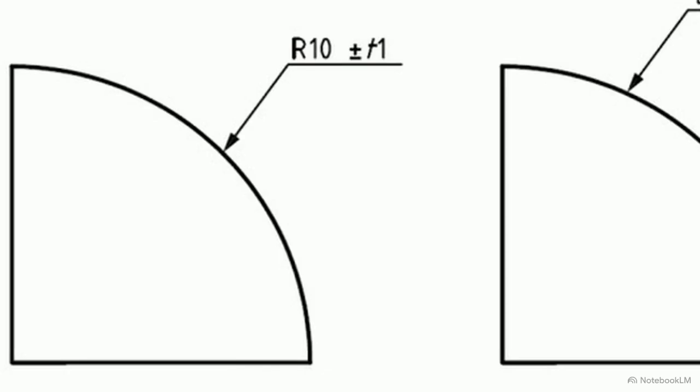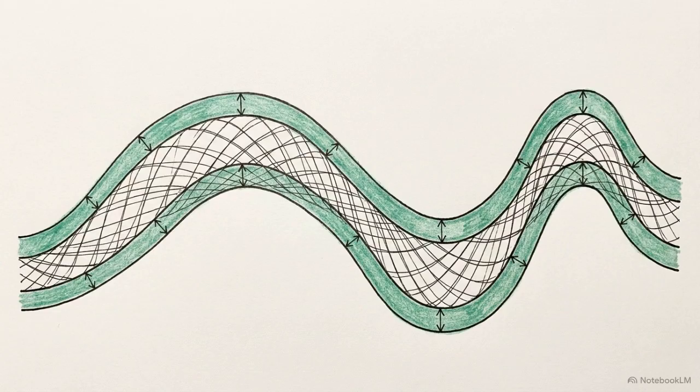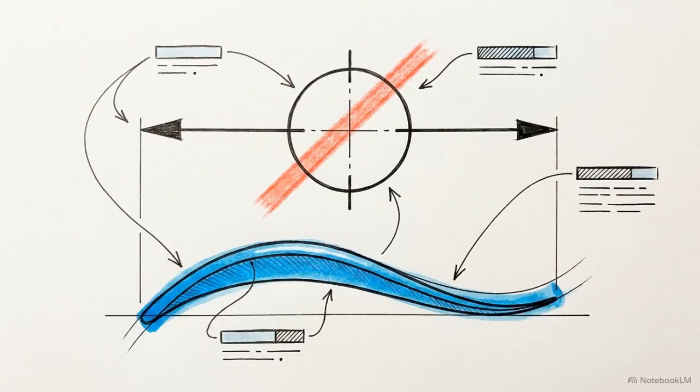control the actual contour. Modern model-based definition requires exactitude. Instead of ambiguous arcs, the system requires a continuous mathematical boundary that hugs the exact shape generated in the CAD environment. Plus-minus tolerances lack the geometric definition required to constrain modern organic geometry.